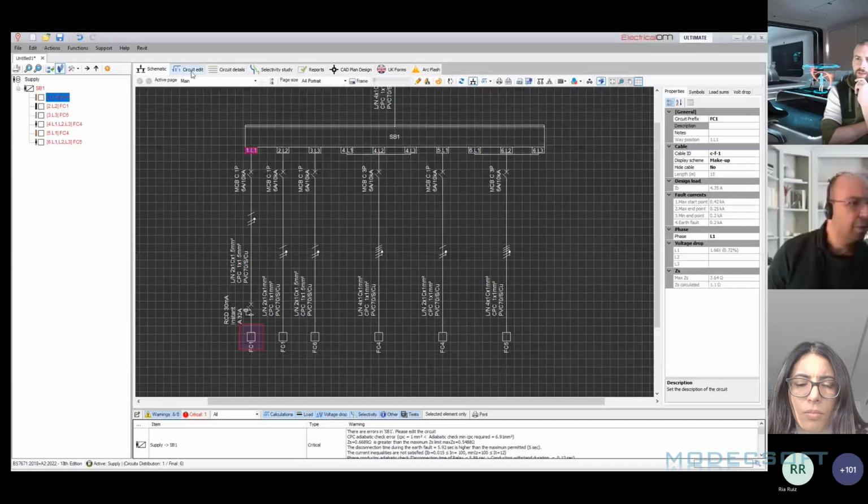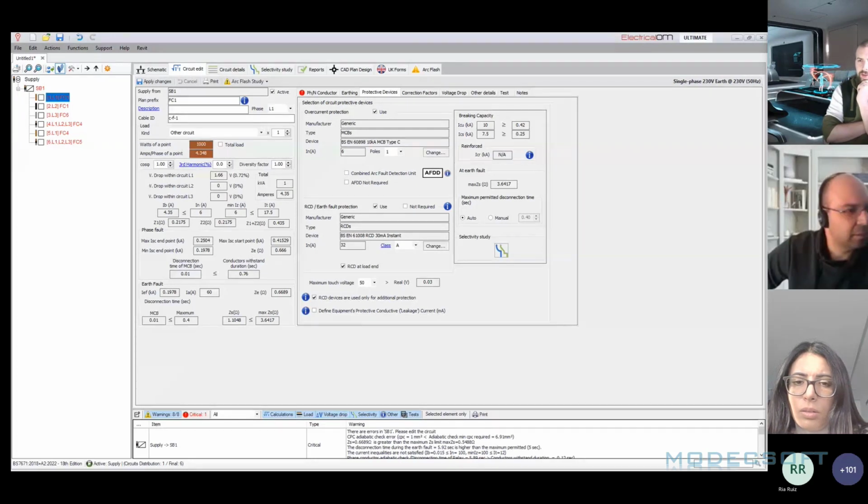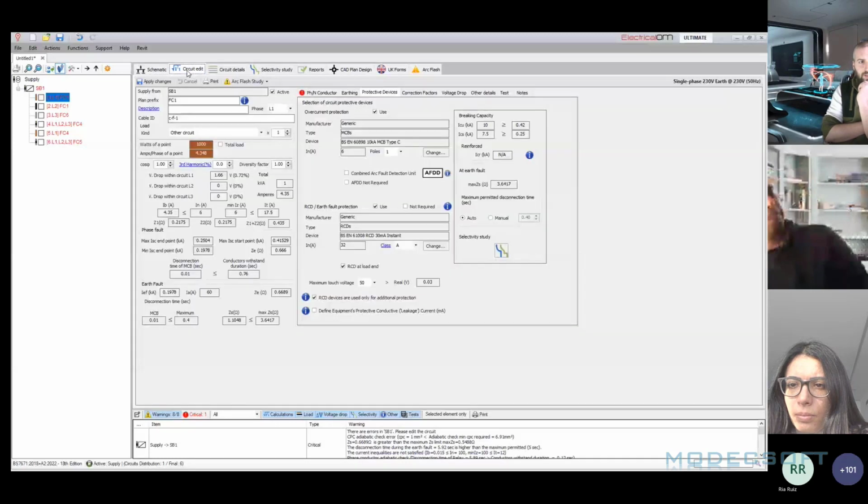Yeah, there were lots of people asking about these sorts of things. We had people doing caravan park installations where they needed to have separate RCDs downstream of the location where the plug points are. We have people in industrial locations using RCD socket outlets with, you know, built-in RCD devices. So we had those sorts of values and things in there. So there's lots of queries about being able to move those around. So hopefully they'll be of use.